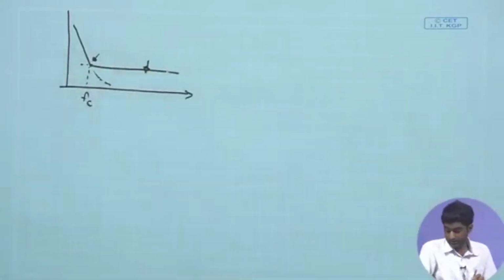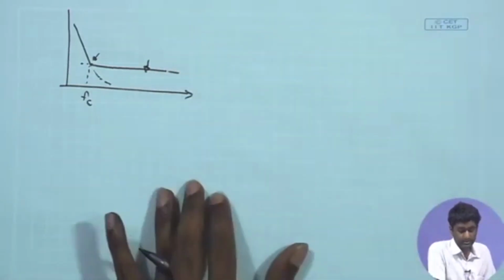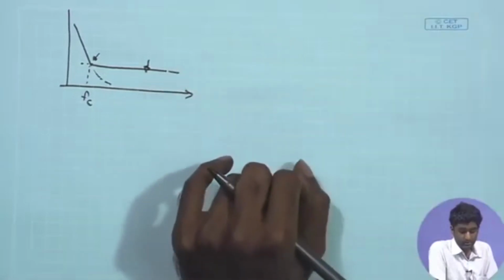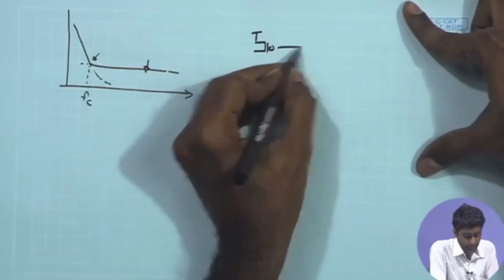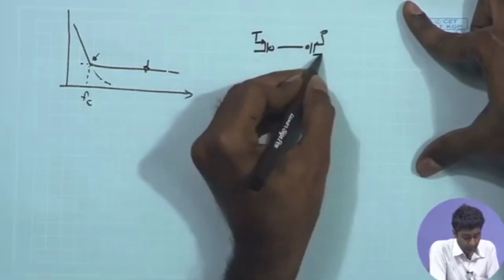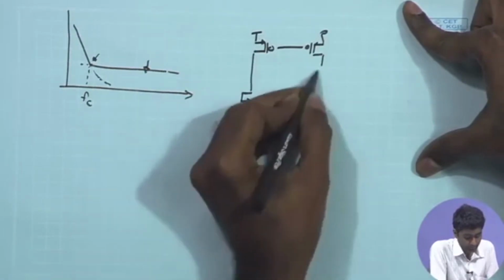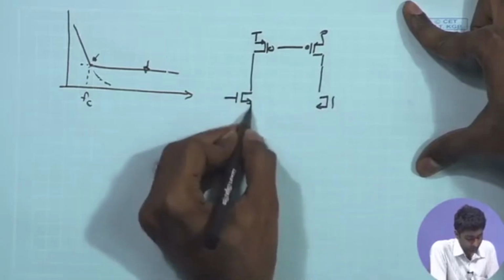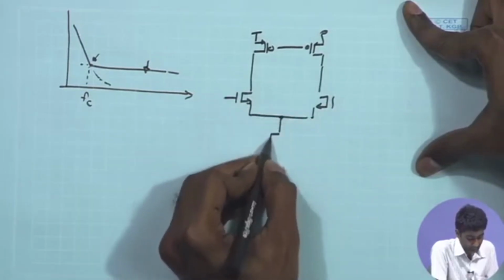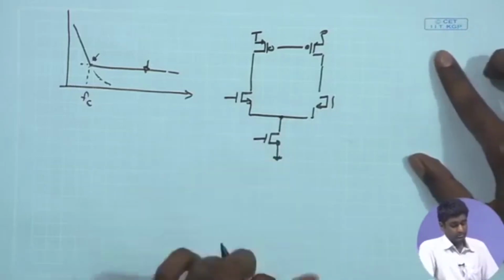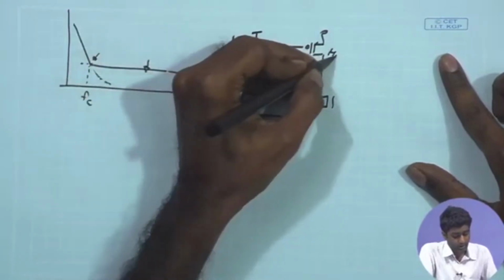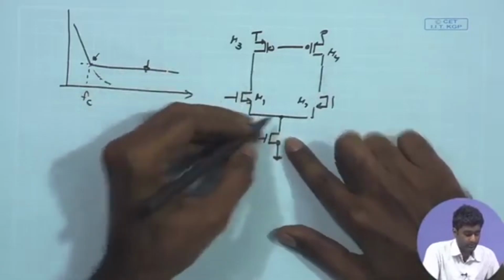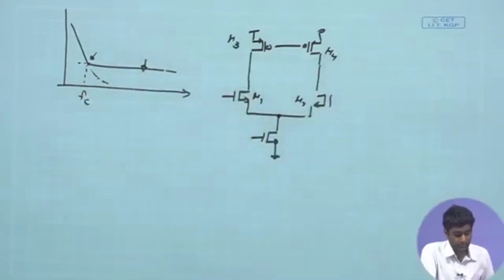So, if we look at the differential amplifier operation, we will be looking at the differential half circuit, and then we can say that ultimately our differential half circuit is going to be same as what we have just analyzed, active load circuit. If we however look at the common mode, we have just got to take care of another transistor which is the tail current source. So, you have M1, M2, M3, M4. For the differential case, we do not have to worry about the tail current source. We said this is AC ground. So, anyway we do not have contribution coming from this one.